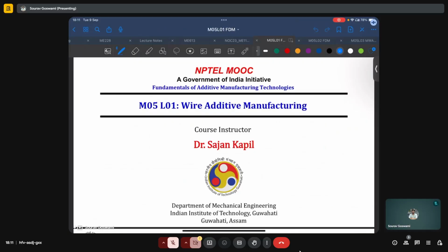Another thing which we noted was that all sheet-based additive manufacturing processes are inherently of a hybrid type because if you just keep on stacking sheets of paper, what you will end up with is a cuboidal volume, and to extract the desired part or geometry out of it, it must be machined in each layer. And thus, inherently, all sheet-based additive manufacturing processes are of the hybrid type.